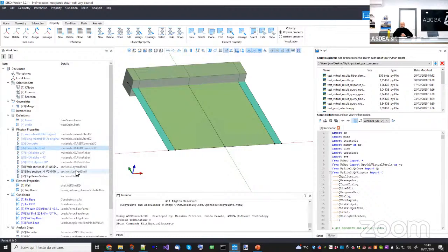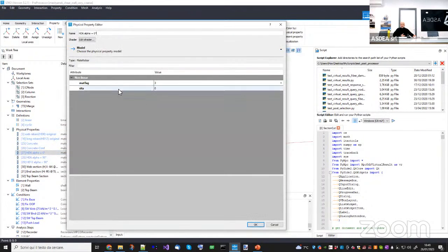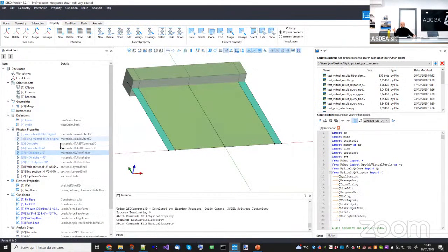From here on, everything is equal to the previous webinar. So basically, I have uniaxial materials. They are being converted into rebar materials with a certain angle. So this is basically a wrapper that converts a uniaxial material into a plane stress material, which is a smeared representation of rebars. For the web, I need 6 diameter rebars with an angle of 0 degrees and 90 degrees. And for the column instead, I just need the vertical, the longitudinal rebars, 90 degrees.